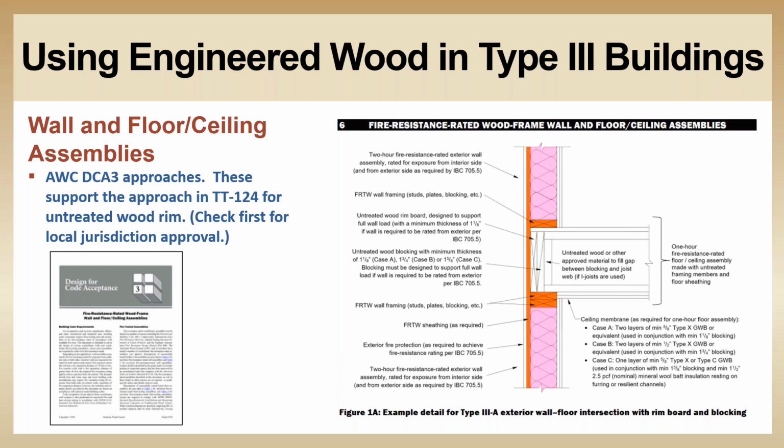Now, one question that comes up is, is the rim part of the wall assembly or the floor assembly? So typically rated wall assemblies don't detail the rim as part of their assembly. I'm not going to get into the details of the multiple wall assemblies available, but note that APA Fire Rated Systems publication provides several options.